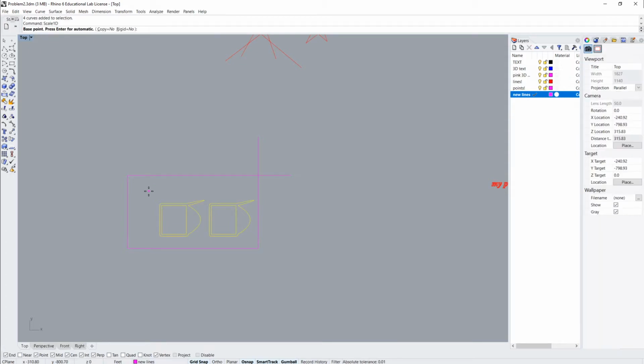So what that does is it lets you pick a dimension, 1D, as in 2D or 3D. So we're just going to scale it in one dimension as opposed to the two that you normally would. So you've got our dimensions here, Y and X. I would just like to scale it in the Y. So I'm going to click in the middle here, click in the middle here, and drag it up. So you can see what it does is actually stretch all of the pieces of that. There's some distortion. You can see this is no longer a full offset from it.